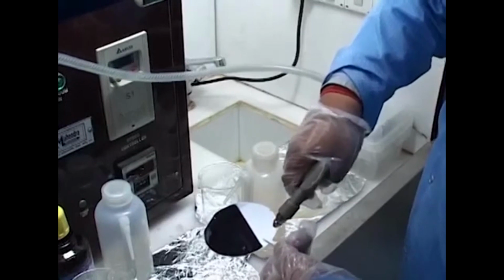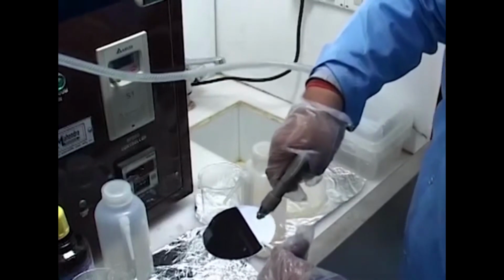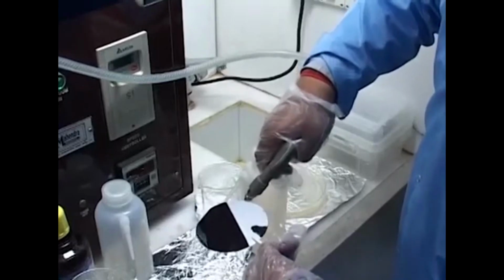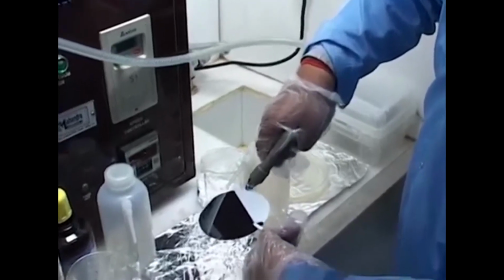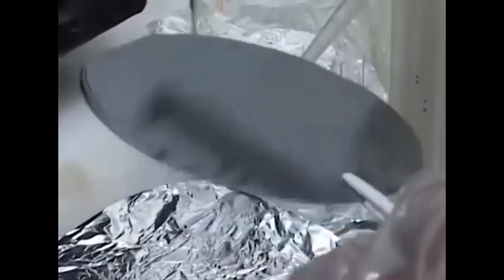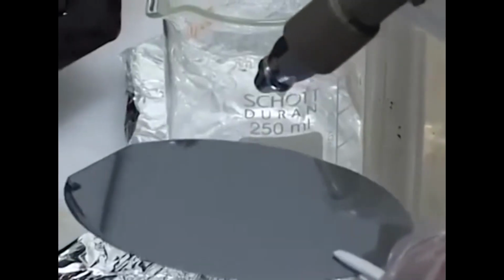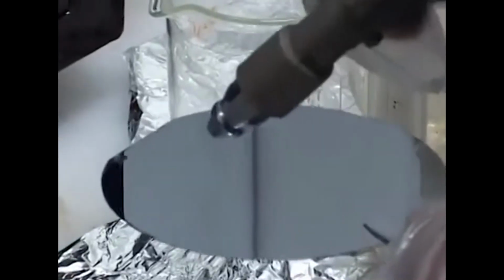Okay, so essentially you have to move this thin film of water in the clean hood away from the side, so that you are actually left with a clean surface of the wafer, a clean shiny surface of the wafer, and there should not be any water drop in this manner on the surface. Typically all the water film should go away from the surface.